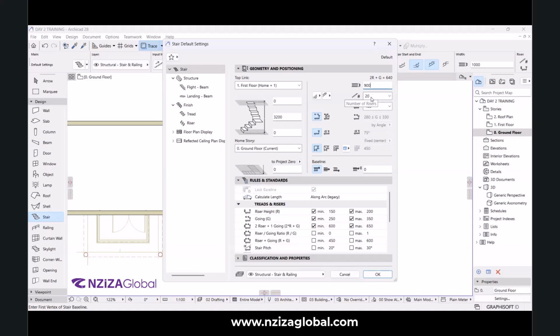When you are designing a stair, you are not allowed to exceed 12 steps per flight. That is according to standard. And it is called a stair when it's above 3 steps. That's when it's called a stair.